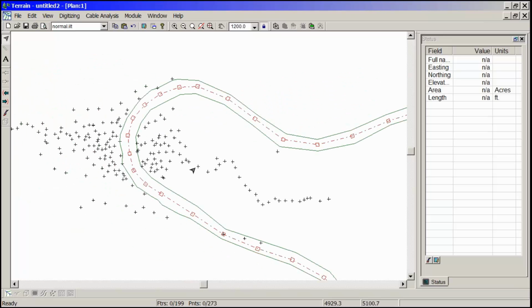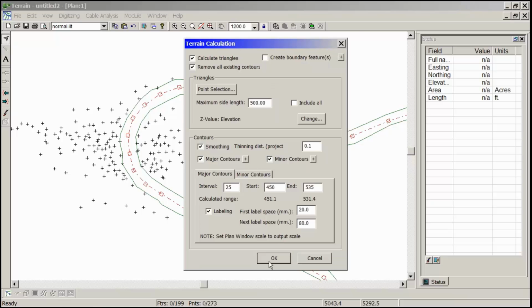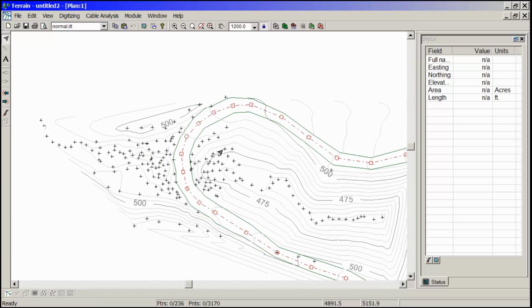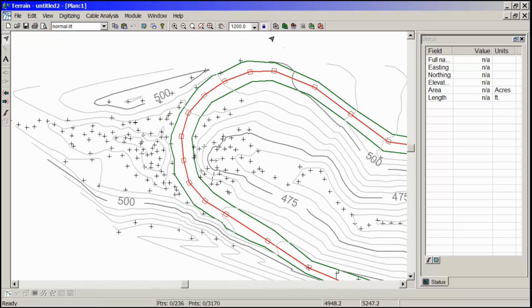Next step is to generate my tin contours. Press the Generate Tin button, which is up here. Okay, we have an area over here which I'm going to replace a culvert. So I'm going to first of all extract the old culvert, or extract the earth in this area, create an excavation, and then I'm going to design an actual pipe arch. Show you how to do that. This is different than what I've done in the past. I'm actually going to create a culvert, a pipe arch for you, and then put it in place, and then design a road over top. Anyway, let's proceed.